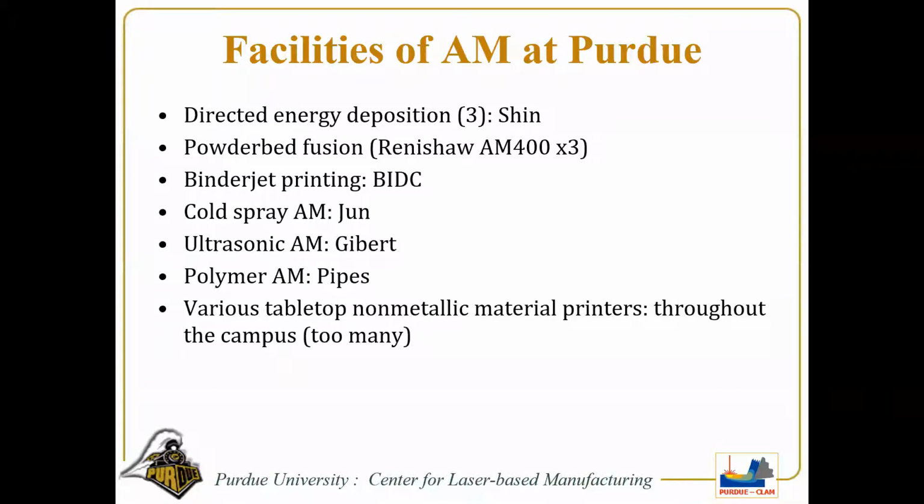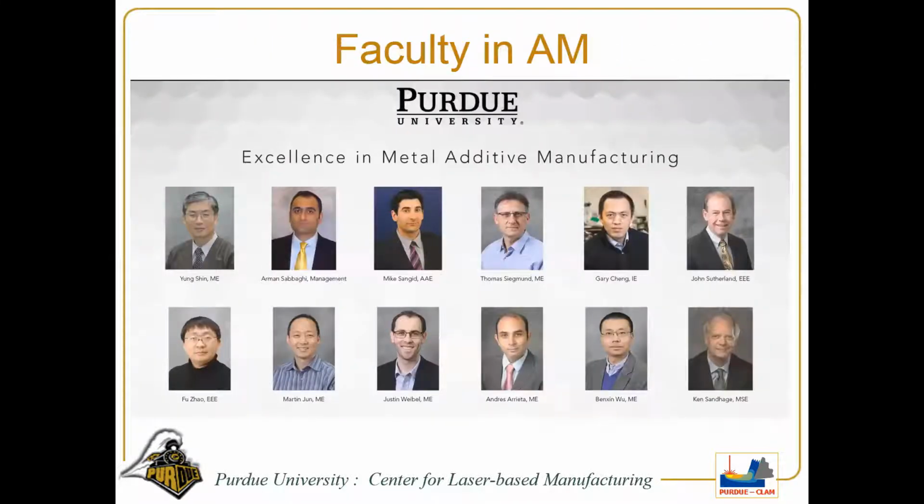And also recently, in my lab, we have developed the capability of doing additive manufacturing in the solid state. It's called the friction stir additive manufacturing process. You don't melt the material, and you just basically plastically deform and bond them, and that has some advantages for materials like aluminum. Okay, so by no means is the list here comprehensive.